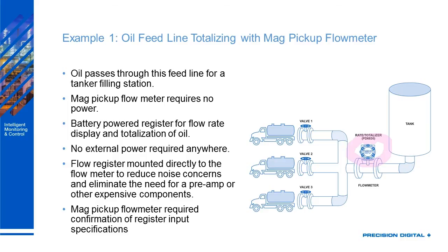In the case of the one you see here, the PD6830, it could sit in this application for 7 years before it needs battery change. And all it's going to be doing is lighting up that LCD, reading in those pulses, and displaying the instantaneous rate and the total that I can reset daily for this application. And that means that I have no external power required anywhere. I've got my flow meter and my totalizer essentially freestanding in the field with no conduit running either.